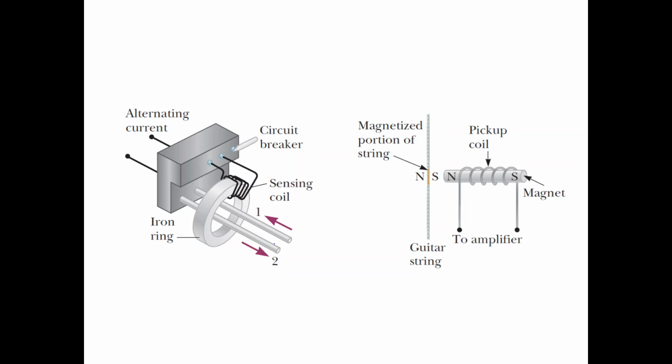So, this is the wire which goes into, let's say, an apartment or house. This is phase and this is zero. We have two wires, so current flows in and flows out. We have this iron core around these two wires.